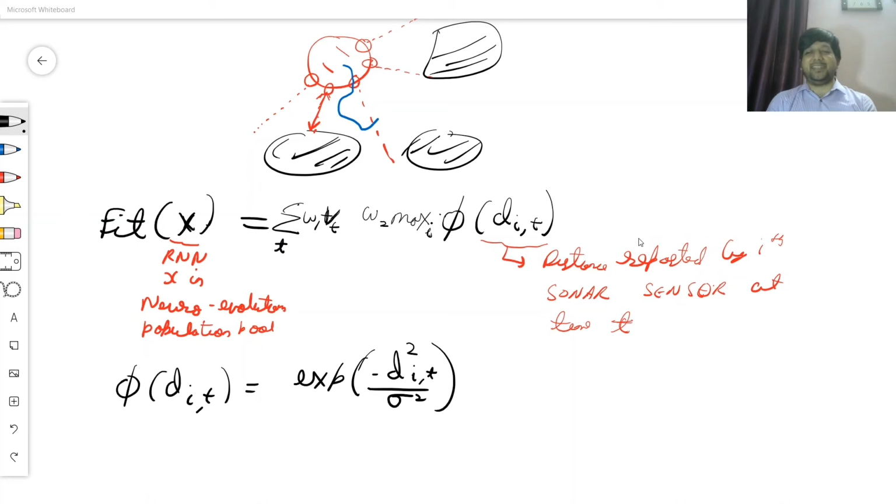You're maximizing linear speed, you are away from the obstacle. However, that's too much zigzag. So I want to tell the robot that taking an angular turn is bad. So let's add it around over here. So W2 times omega t, the angular speed at time t, and again I need to minimize it.